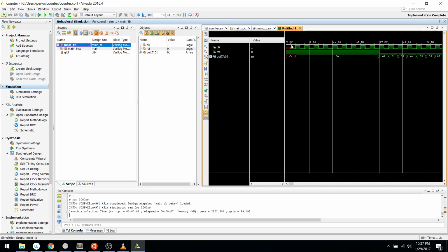So you can see we don't set the clock initially. That's why, initially, we start with reset asserted high, and then we do a bunch of cycles. And you can see on the first rising edge after reset is high, the default value 0 gets latched into the output register. And then even though it's doing a bunch of cycles, this thing is not changing.